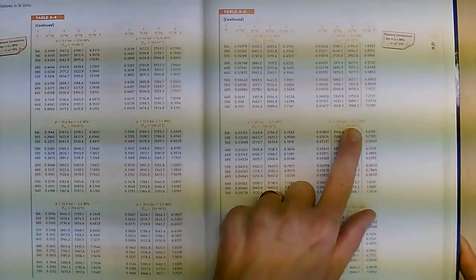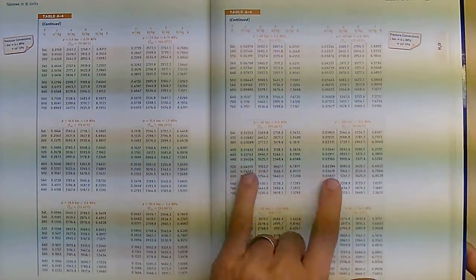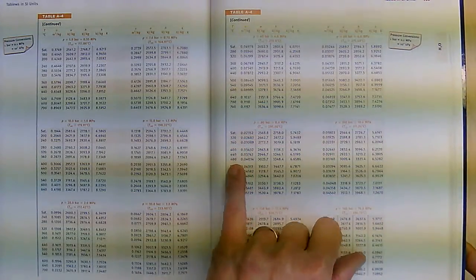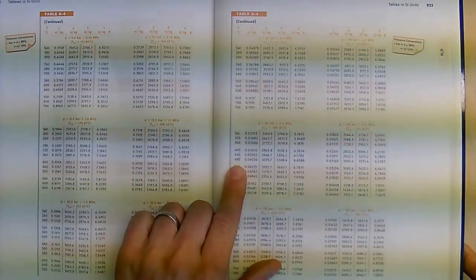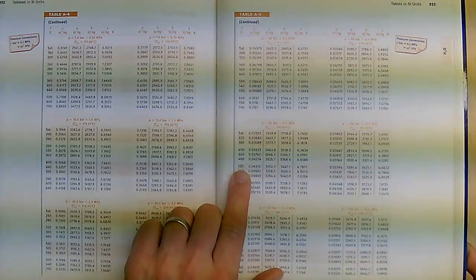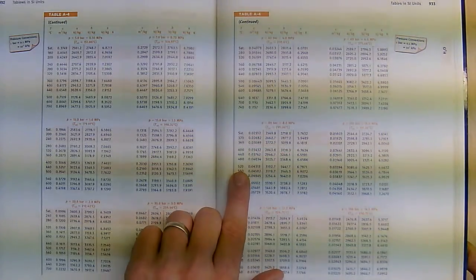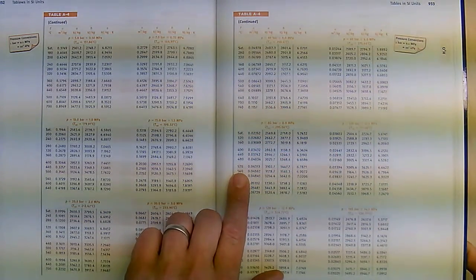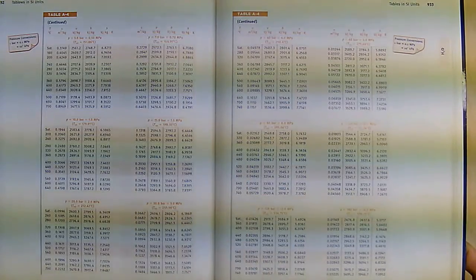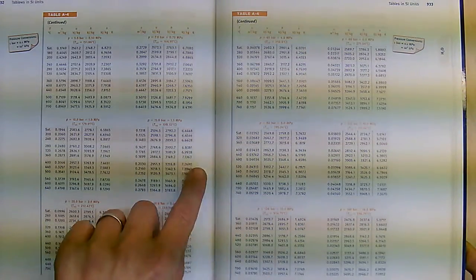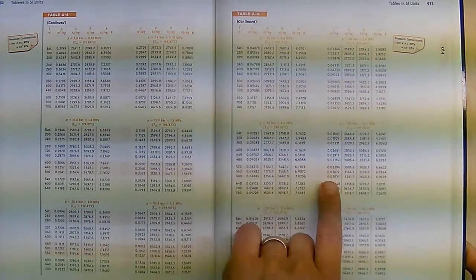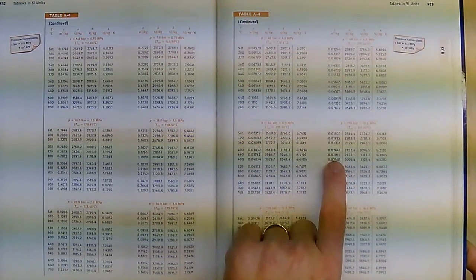Now I'm going to go to 10 megapascals, which again is 100 bar. And I notice down here I've got my temperatures, and you can see I've got 480 and 520. I'm at 485, so we'll figure out how far between that, but 5/40ths, maybe 10% or something. So that means I'm somewhere in between the